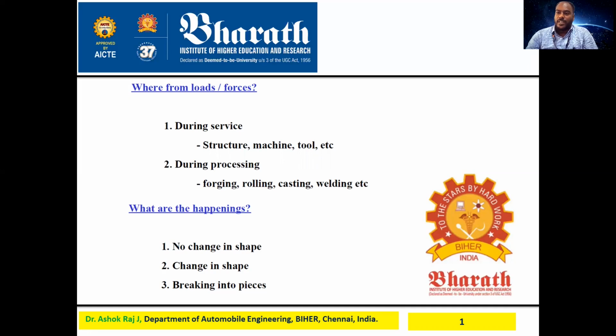While doing the machining, you have to hold the sample. You have to tighten it, otherwise it will be misplaced or you cannot get the proper size and shape, especially in the lathe machine. If while tightening or removing, your material gets damaged due to the external force, what will happen?